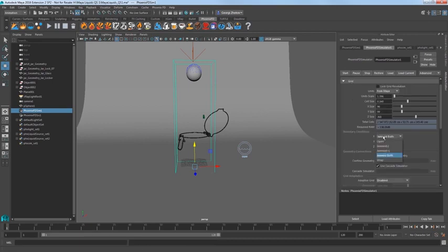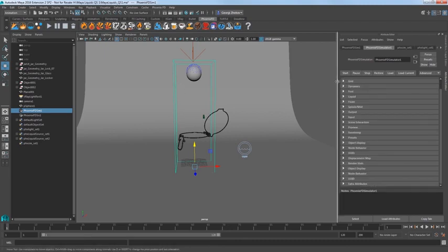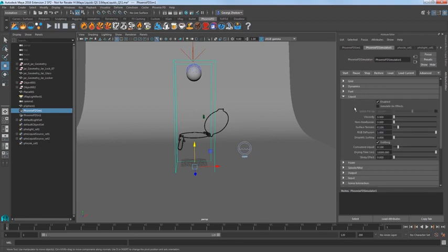boundary conditions, set the X, Y, and Z walls to be open. This will keep any of those droplets from colliding with imaginary walls. Then go to the liquid section and set the consumed liquid attribute to 0. This also relates to the wetting parameter, which creates these red particles we see wetting the inside of the jar, creating a wet map. By setting consumed liquid to 0, we are preserving all the liquid with none of it evaporating away. So now let's fix the spreading out of the pour as the emitter stops discharging.